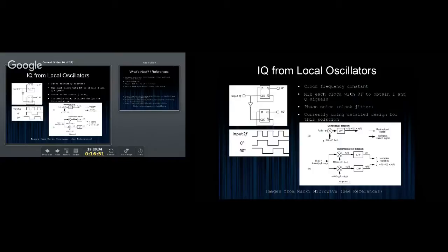And this here is the hypothetical, or theoretical, architecture of a system that takes the intermediate frequency in. Now this would have to be a lot higher because this down or up converts, so you can't convert to the same frequency. If you're going to take 10 megahertz and generate signals at 10 megahertz, you need to convert to a different frequency first and then return back down to it. So there's all sorts of design decisions about choosing frequencies in relation to filters that are already available, and all this kind of stuff.